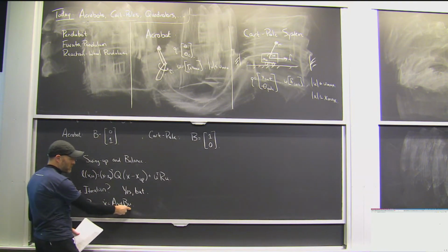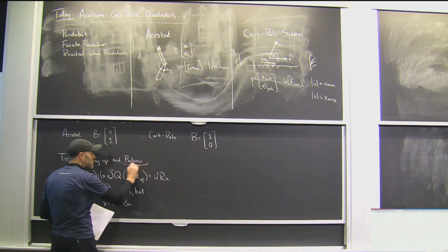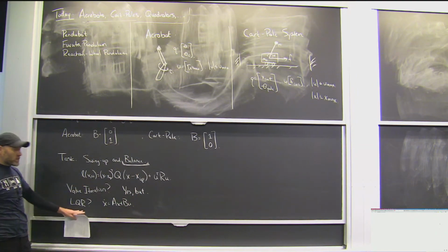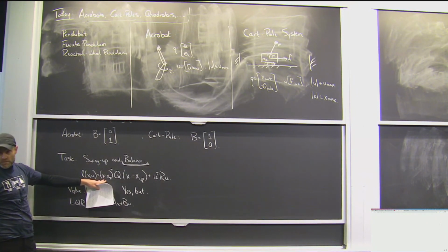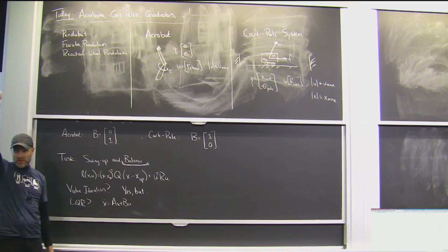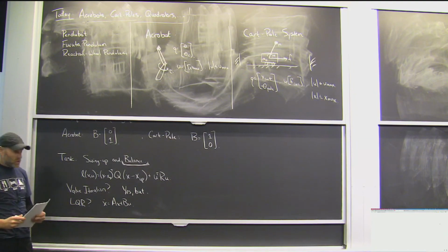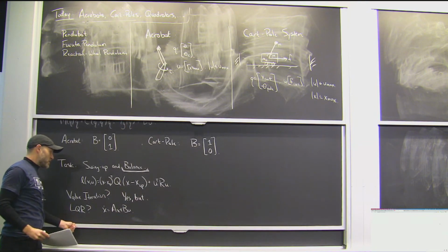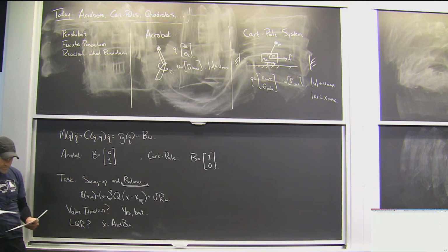So the question is, how far can I get with something like LQR on these systems? And the answer, maybe you won't be surprised, but we'll see in some detail here, is that for the balancing portion, once I'm sort of close to the right solution, actually LQR is going to be an excellent solution. It's going to be a local approximation of the true solution of this problem, and it's going to be good in the balancing regime. But it's going to be insufficient to do the swing up problem. But because we can understand so much about these systems in this dimensionality, I think seeing how well LQR does and understanding its limits is going to be very useful.